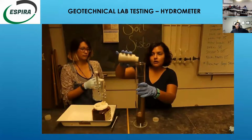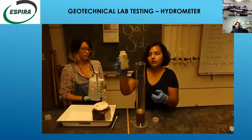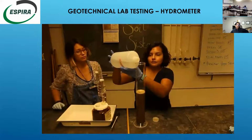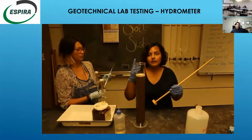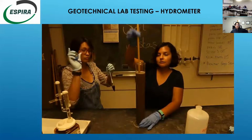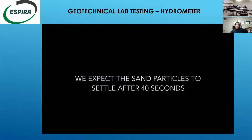So we'll take the plunger out and add our solution to this sedimentation jar. You want to be sure whenever you're doing this in the future that you rinse out the inside, so that you get everything from your shaking jar into your sedimentation jar. Now we're going to use a plunger to resuspend everything in the sedimentation jar. And then as soon as I take this out, Amy is going to set in the hydrometer and time for 40 seconds.